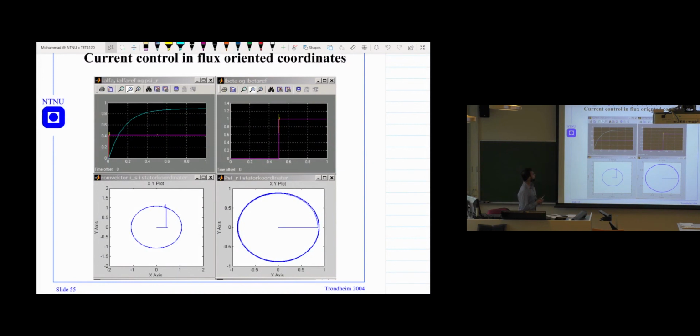And also I was saying that it's taking much longer for the rotor flux, because the process delay is much longer, 200-300 milliseconds for the rotor flux time constant. So it's taking much longer to reach the reference value like 0.9. Even though we provide the current here, it takes much longer to reach there because of the delay that we have already seen. While the Q-axis component, the beta axis component, follows the torque very efficiently.